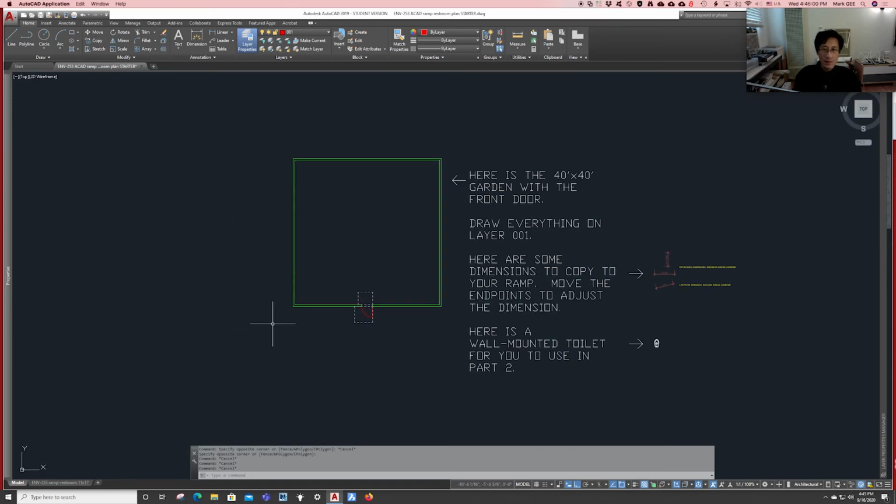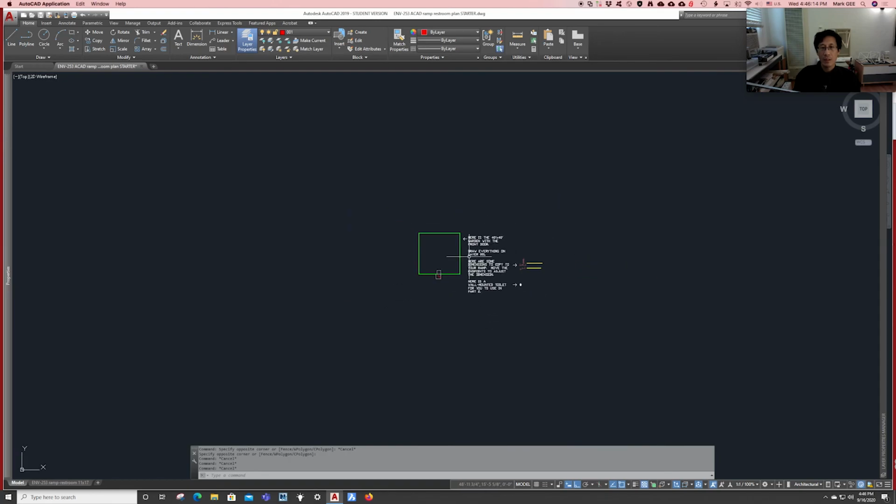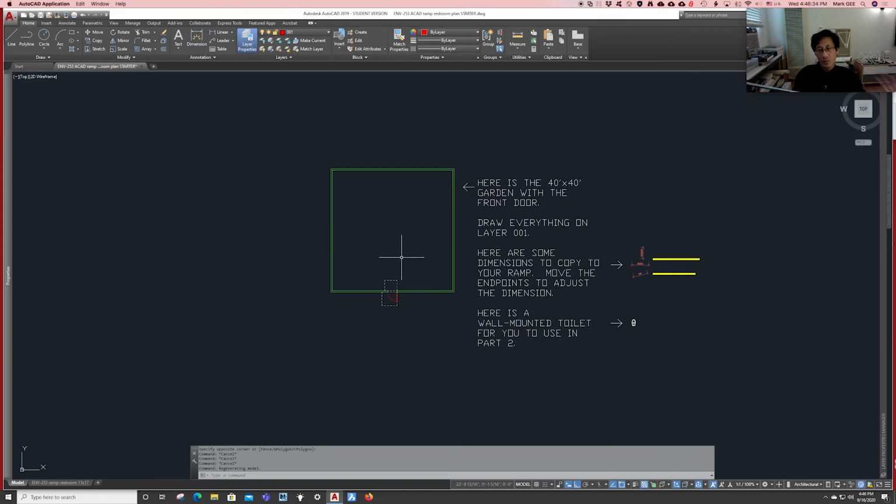All right, so again, just to reiterate a few of the important interface items and how AutoCAD, the program, is structured and used. First of all, when you open up the file here, you'll see that we are in this dark black background, sort of infinite space where there's kind of nothingness around. You might have a grid here, and I think that's on by default. I do not like the grid. I don't think many people like the grid. It's a kind of arbitrary grid spacing as far as I know. I've never used the grid. Go into the preferences, you can turn it off.